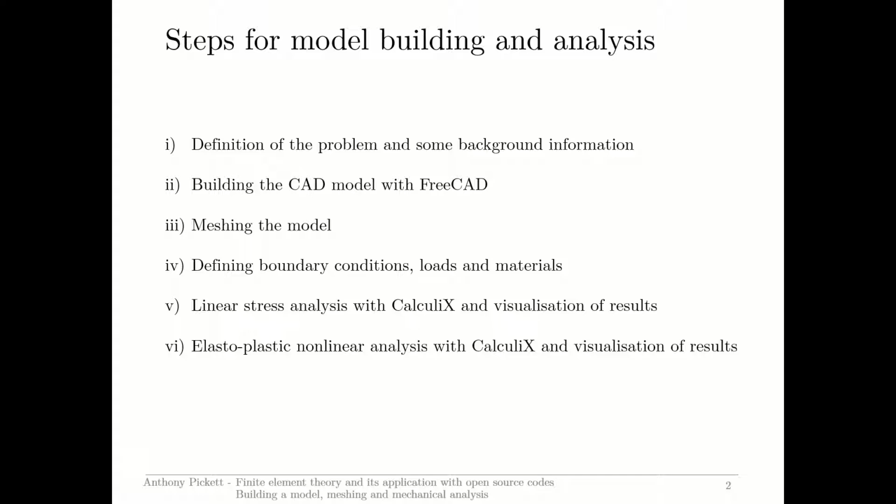I'll demonstrate the meshing. We can experiment a bit with different meshing possibilities within FreeCAD. Then I'll define boundary conditions, loads, and materials, and then we move on to the analysis. As I mentioned, first of all, we'll have a linear stress analysis using CalculiX, and then visualization of these results. And then I'll move on to an elasto-plastic stress analysis. So this becomes then a nonlinear problem.